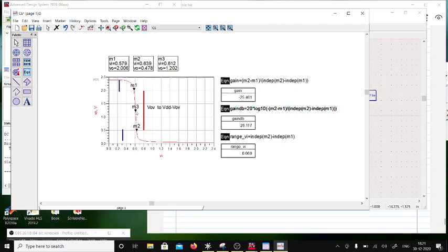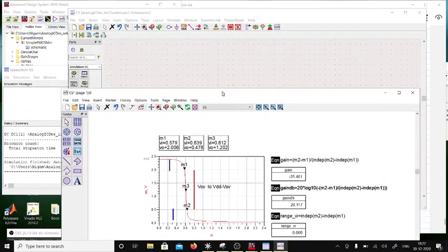So your bias point is around M3, which is 0.612. So you can go 30 millivolts on the left and 30 millivolts on the right. So your input voltage range has shrunk because the gain has gone up, sorry. So if this is the scenario and you bias the part at 0.612 and suddenly there is, let's say, temperature variation, VT changes.